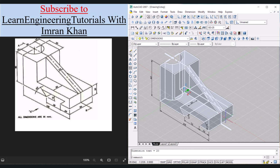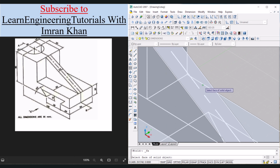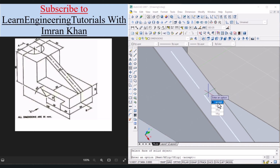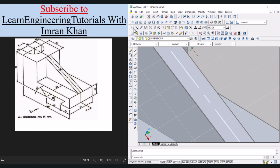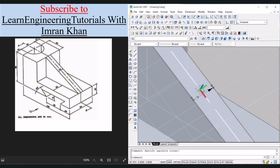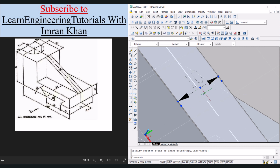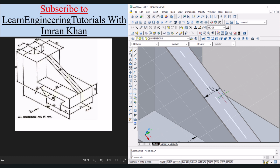Now we have to change the face again. Click on this face UCS icon, select this face, don't click on the line, you have to click on this empty area which shows that this is the face. Click on accept, click on linear, click on the opposite perpendicular point. You can see the 10 value, click on this 10 value and now move it a little bit so we can see them clearly. Press escape.